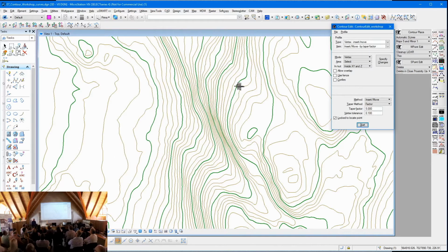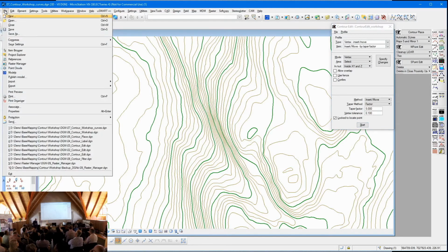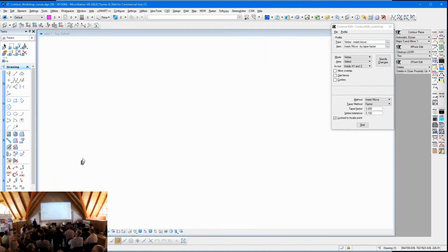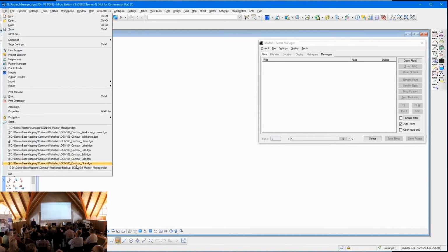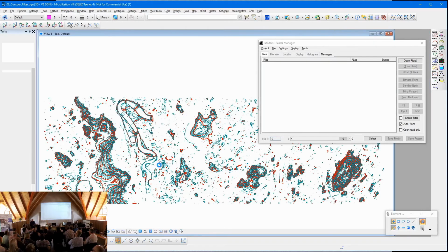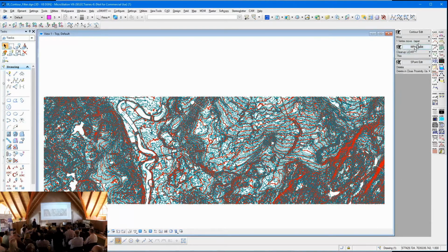So now we've got this metadata that we've added. Remember, the metadata is extra information that's added to the contour, such as the surveyor, etc. Now we're going to say we want to filter on this, and we're going to show you combinations of filters. That might be quite useful for that type of job where you've now recreated contours in an area. So we've got the survey.